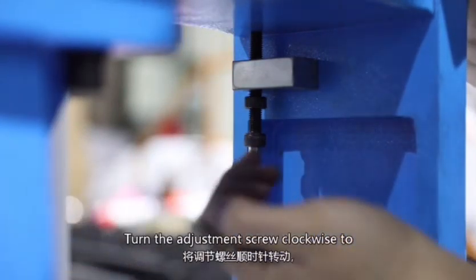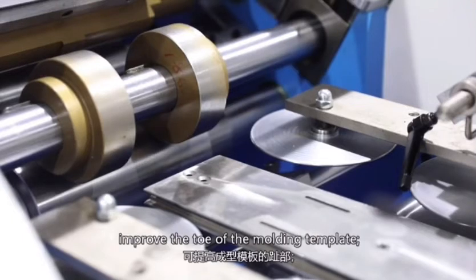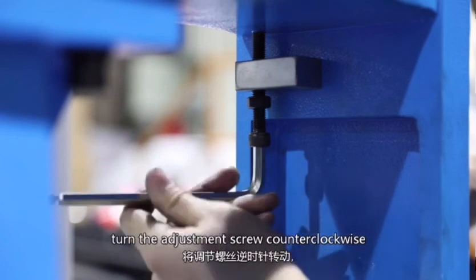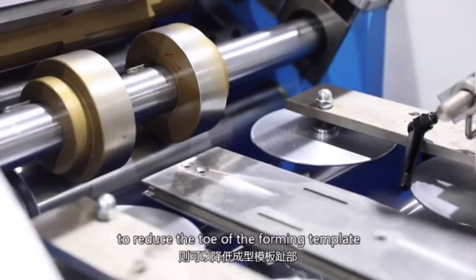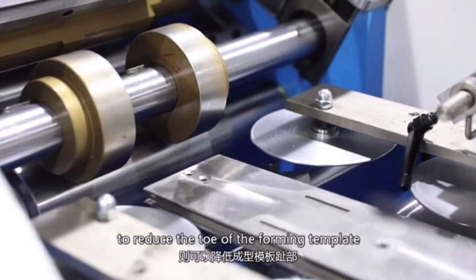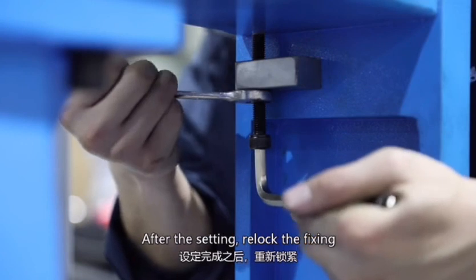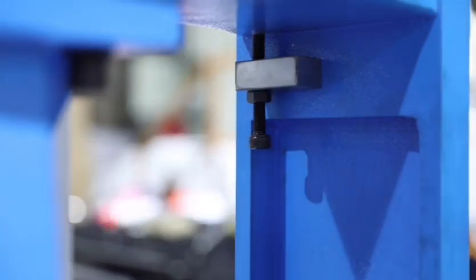Turn the adjustment screw clockwise to increase the toe of the molding template. Turn the adjustment screw counterclockwise to reduce the toe of the forming template. After the setting, relock the fixing screw of the adjustment screw.